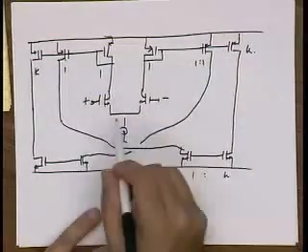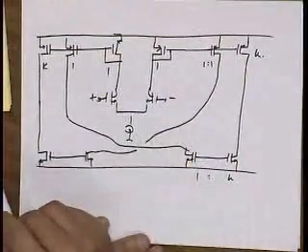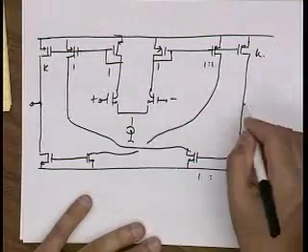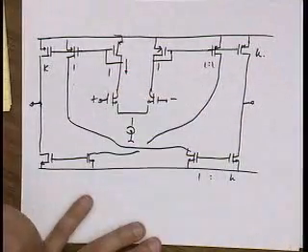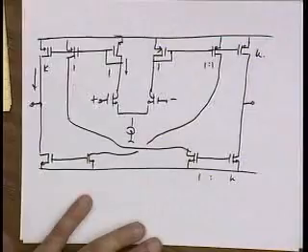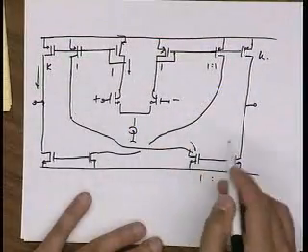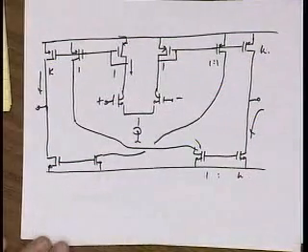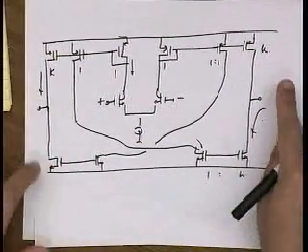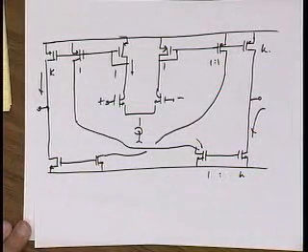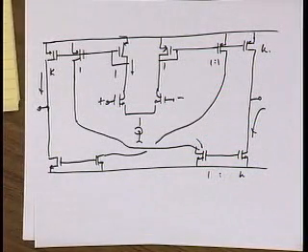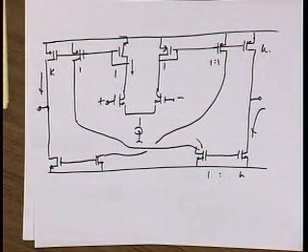So now, when let's say we get into the same condition where I'm slew rate limiting, so I'm pulling all my current here and dumping it into the load here. Now I also take a copy of this current, mirror it over here, and pull it out of here. So now this will slew both directions symmetrically. Okay, questions?